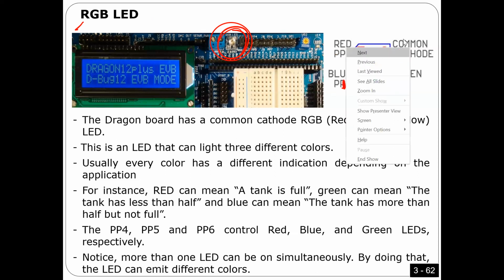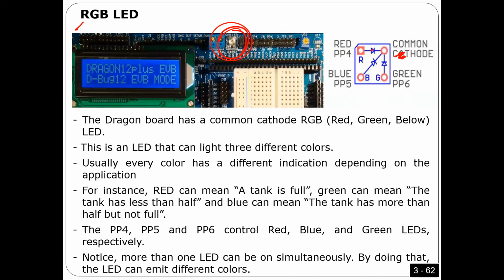Also here, if you want to make it clear, you can just put 1 here, and then put 0 and 0 here, and so on. Okay, guys? Very simple. I was playing. I love the topic. This LED is not designed to mix colors. It is designed to give only 1 color. That's why, if you want to use it correctly, only one pin should be 1 at a time.